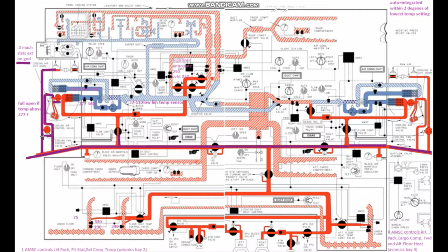And then this bottom torque motor will modulate the amount of bleed air that will go to our cooling fan, which is kind of depicted up here. And the cooling fan will turn, sucking in air through the ram inlet, and then it'll blow it across our primary heat exchanger right here and our secondary heat exchanger right here, basically cooling the air that's going into those heat exchangers, the primary and kind of secondary cooling stages.